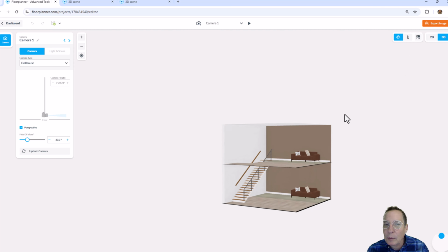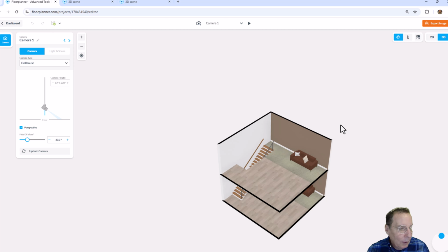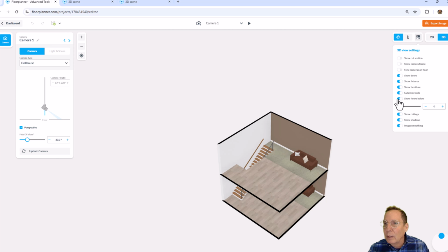Sorry to tell you, but those do not work looking upward, but they do work looking downward. If you have to do some mezzanines or other areas, you might want to consider actually building your entire multi-story on one floor and using those surface commands to make custom floors up above, which will allow you to be looking through the space upward. But for downward looking, the cutaway cutout feature to apply to a surface outline really does come in handy.